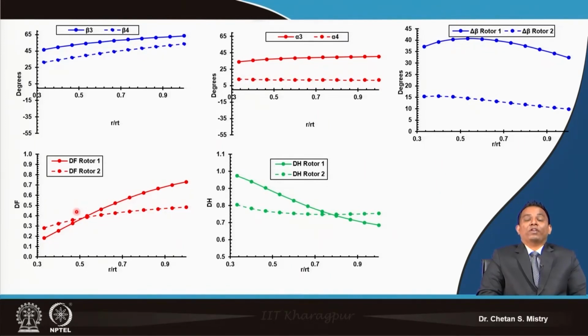So, when we are doing our design for a contra-rotating fan, you need to design your rotor 1 nicely. Finalize all parameters using your Excel sheet program. Once you are confident, then you go with the design of rotor 2, because they are interrelated. A small change in rotor 1 may bring more change in rotor 2. So, be careful about these aspects.